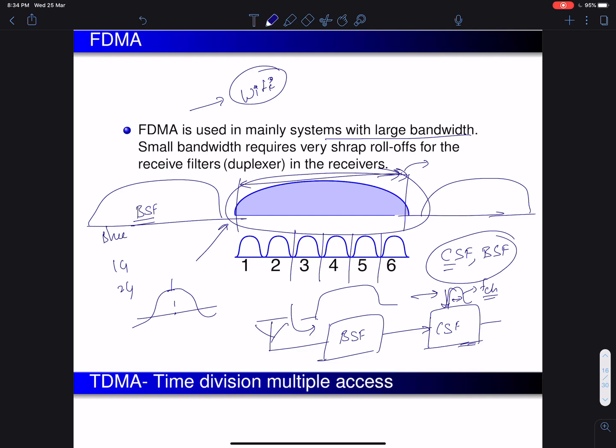When I say roll off, what I mean is the attenuation, how fast the signal is rolling off. Once, let's say, you encounter a pole, your filter response will start reducing. The rate at which it falls off, roll off gives you an idea for that. A good filter needs to have very high roll offs. A good band reject filter, or a filter that can reject some frequencies, should have very good roll off. If the roll off is poor, then it's going to look like this, so you are passing all these frequencies which you still don't want to.